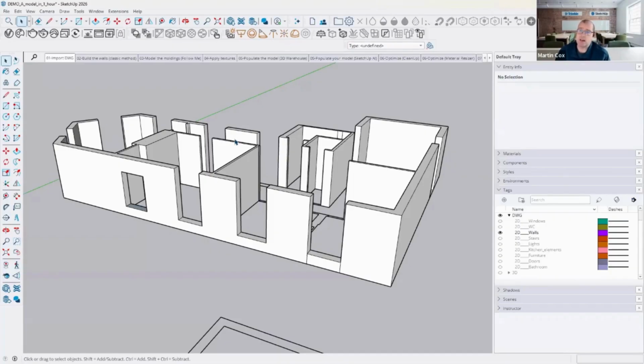Also, what's quite important is components are a fantastic way if you have lots of things within the same file that are the same. So a company I worked with, they were a perfume company. They had like 600 bottles within their shop. They were the same bottle, but by using components, it meant that SketchUp only loaded the one bottle and then said this bottle is in these 600 locations. It really helped with a lot of information.